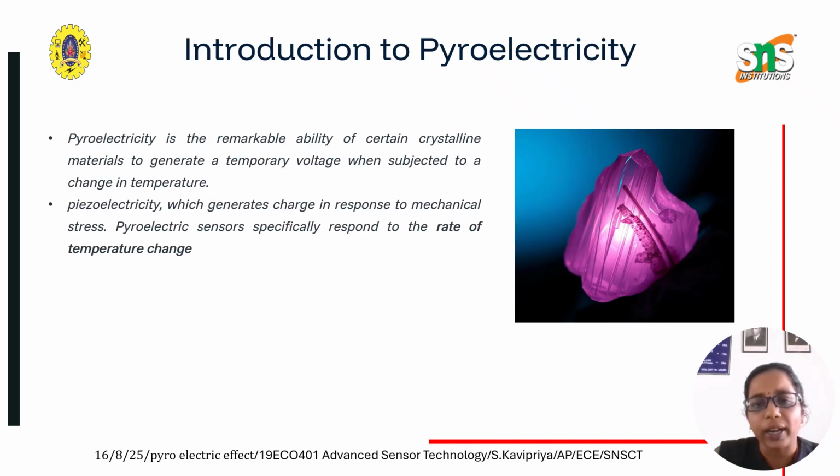And next is pyroelectricity. In piezoelectricity, when a stress is applied to a crystalline structure, it generates an electric voltage. Whereas in pyroelectricity, the electrical signal is generated whenever there is a change in temperature, a temporary voltage generated whenever the crystalline structure is subjected to a change in temperature. In piezoelectricity there is generation of charge in response to mechanical stress, while pyroelectric sensors respond to the rate of temperature change.